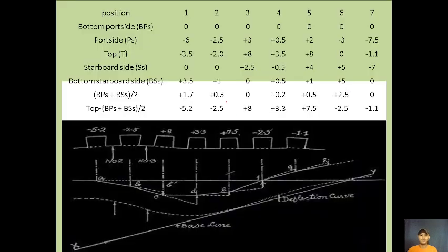Okay, so if the crankshaft, we will check the manual, we will check the sea trial, the acceptance test record. We will check if all your readings are normal, near the previous readings or the sea trial readings, and also check if it's still good based on the manual.